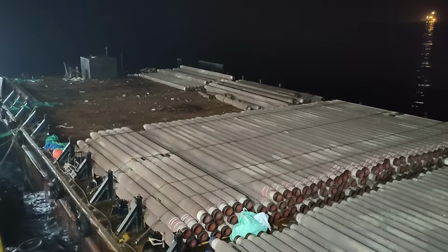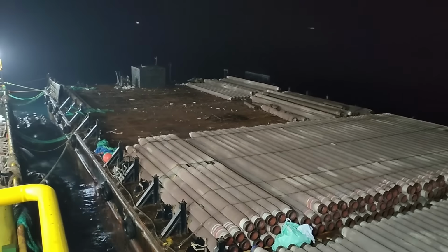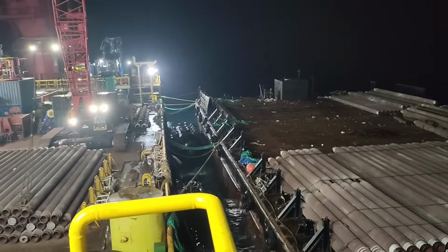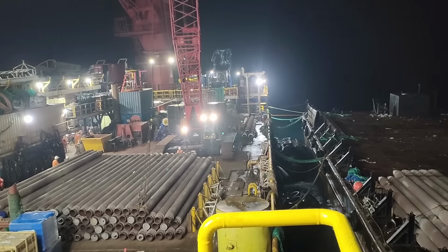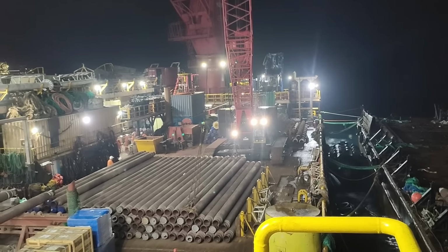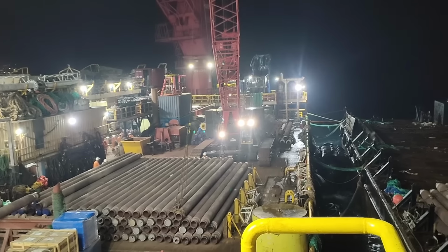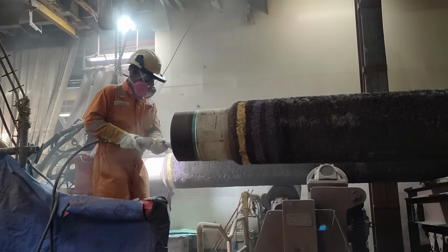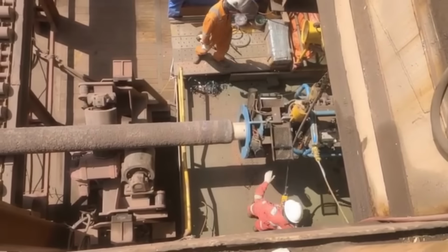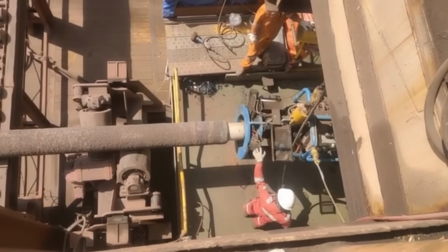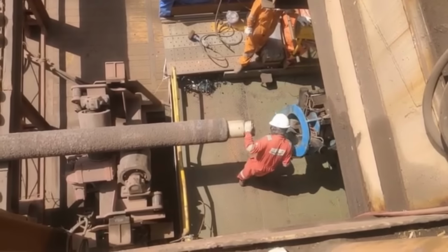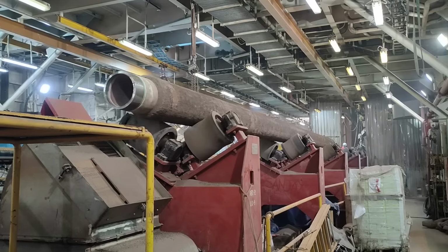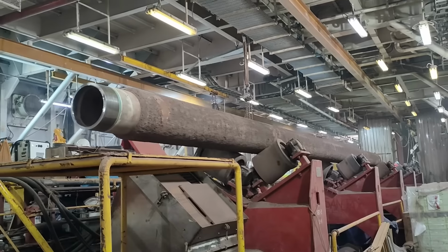seabed. 12-meter segments of pipes are supplied to the lay barge by pipe barges. Pipes are first transferred to the lay barge. Once the pipes are on the rack, initial cleaning of the steel surface is done, and after that the pipes are beveled at both ends for better welding. After this, the pipes are transferred to the ready rack.